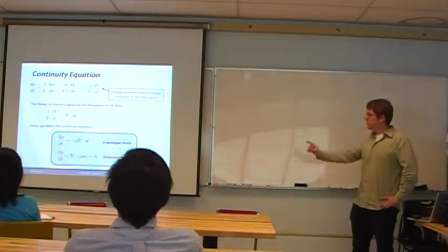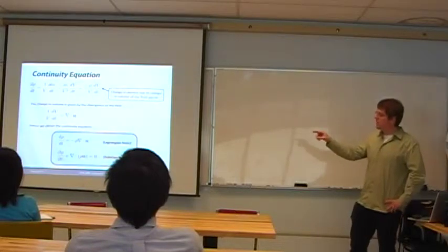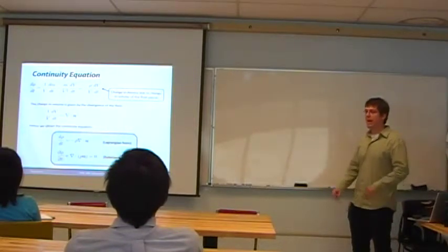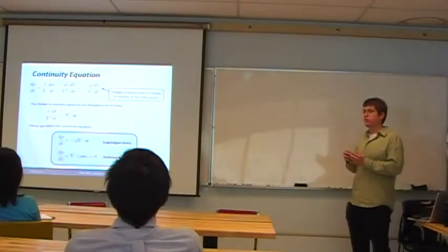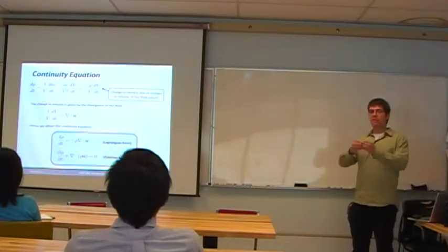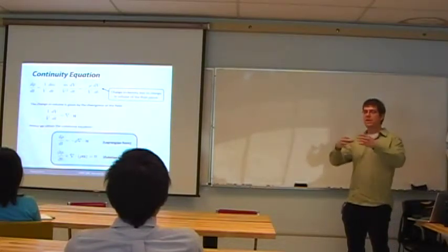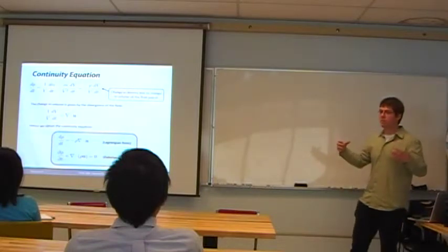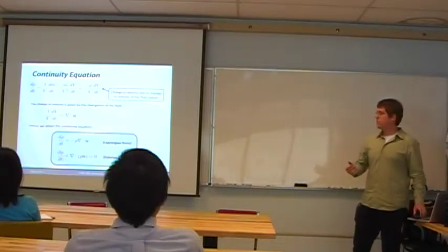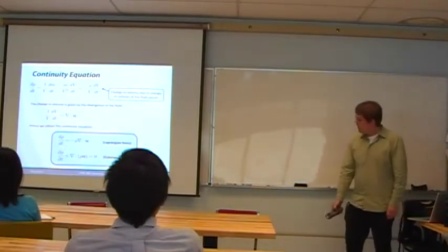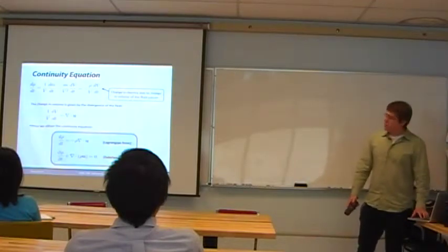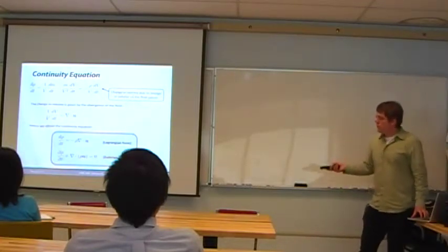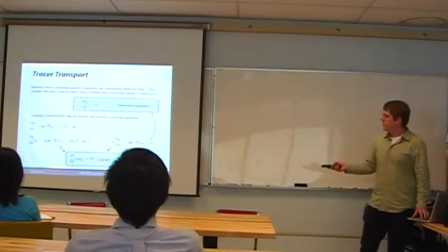Negative, yes. So if div dot u is positive and density is positive, the right-hand side is going to be negative. Hence, the density will decrease with respect to time. And that's what you would expect. If you have a fluid parcel that expands while maintaining the same mass, then the density of the fluid parcel has to decrease in order to remain consistent. All right. So that gives us the continuity equation that we're going to be using in Eulerian form.